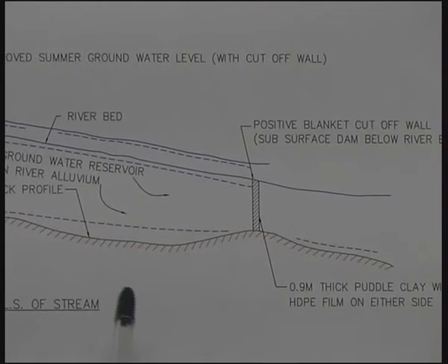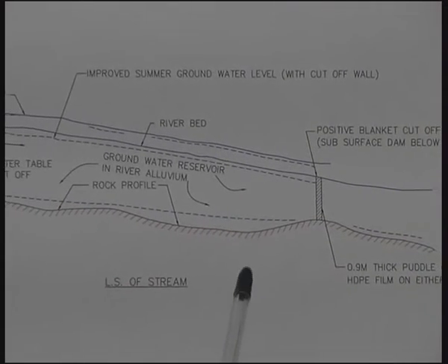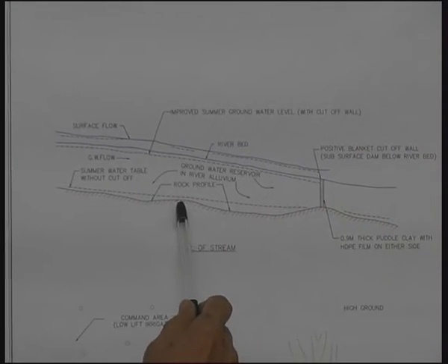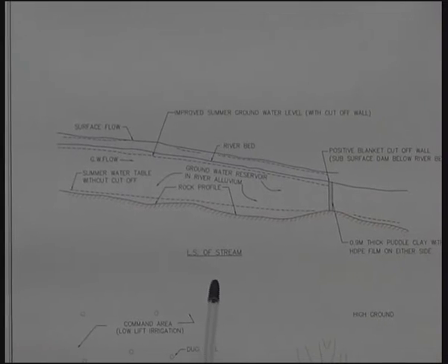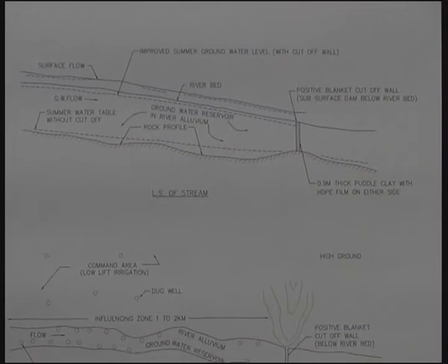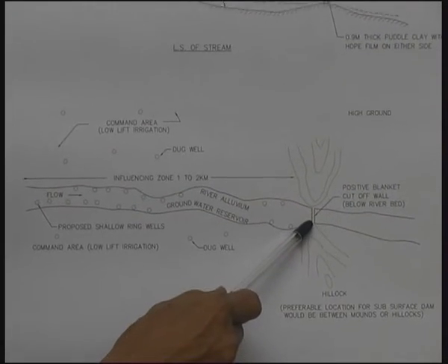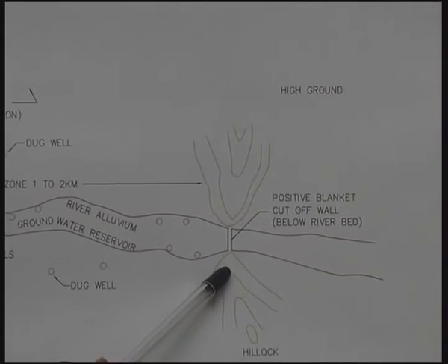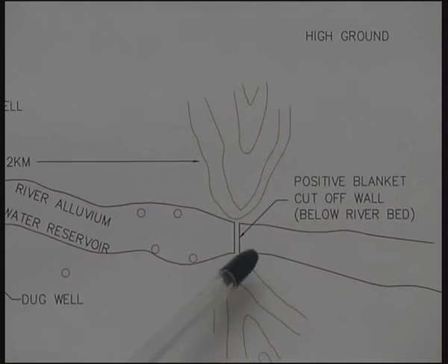So geophysical soundings will have to be taken in the stream course at certain grid intervals, which the geoscientist would be able to determine, and it is possible to determine this profile of bedrock, and also it is possible to get the end connections. For example, the subsurface dam will not be only within the stream, but it has got to be extended on either side till it meets hard rock at a level higher than the bed of the stream. So this I will explain in another sketch.